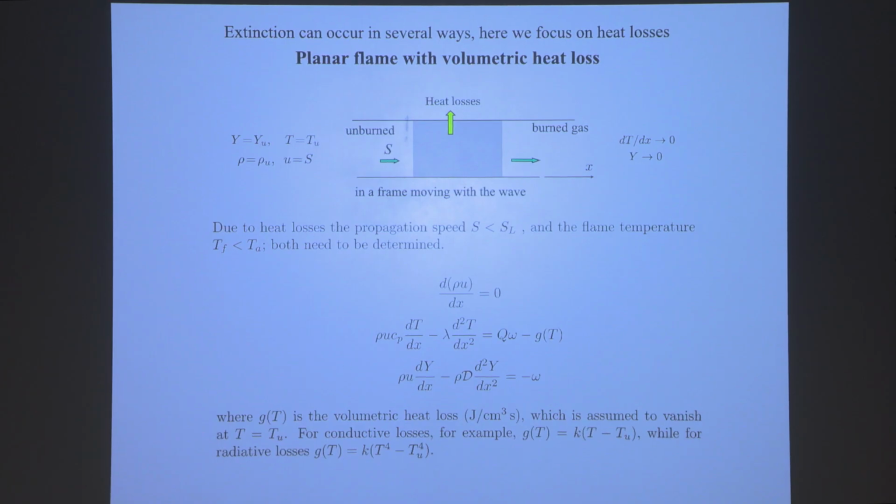this problem. Again, we are using only a single reactant, so let's say lean, the fuel, and the governing equations are going to be the continuity or conservation of mass. Rho u is a constant, so it gets pulled out here, and you have the energy equation and the species equation, with the rate of consumption of the reactant. By the way, I didn't say that explicitly, but I think it's obvious to all of you who have been working on combustion that always in the species equation, that term is negative because it's consumed, and in the energy equation it's positive because it produces heat.